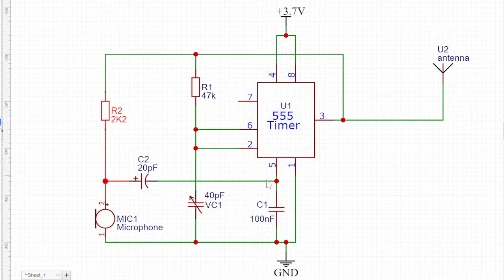Now you might be wondering how this works. We had a video on how 555 timers work. Please go watch that video because we already made it. There are 2 comparators inside this 555 timer, so it's constantly checking the inverting and non-inverting input voltages, and whenever the non-inverting input is equal or greater than the inverting input, the output is high. So we did some very detailed analysis on that. So that's how this basically works.